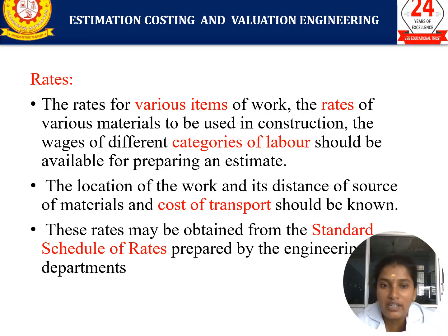And also the rate, because each and every item of work depends upon various rates. The main rates we are taking from the schedules of rate. So who will prepare the schedules of rate? It is the standard schedule of rates that will be prepared by the engineering departments. It changes once a year. So we are taking the total cost and each and every material cost from the schedules of rate, right?